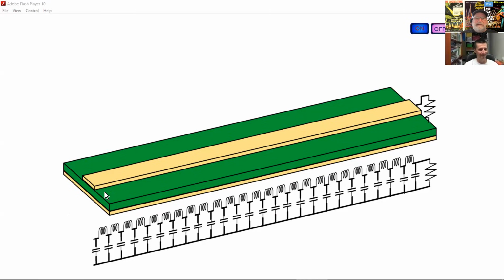And you think, wait, I have this insulating dielectric between the signal and the return. How could you possibly get current flowing between the signal and the return conductor if it doesn't go all the way down? And the answer, the secret to understanding return current, is displacement current. Displacement current is a concept that James Clerk Maxwell introduced in the 1860s, and that was one of the most important innovations that he contributed.